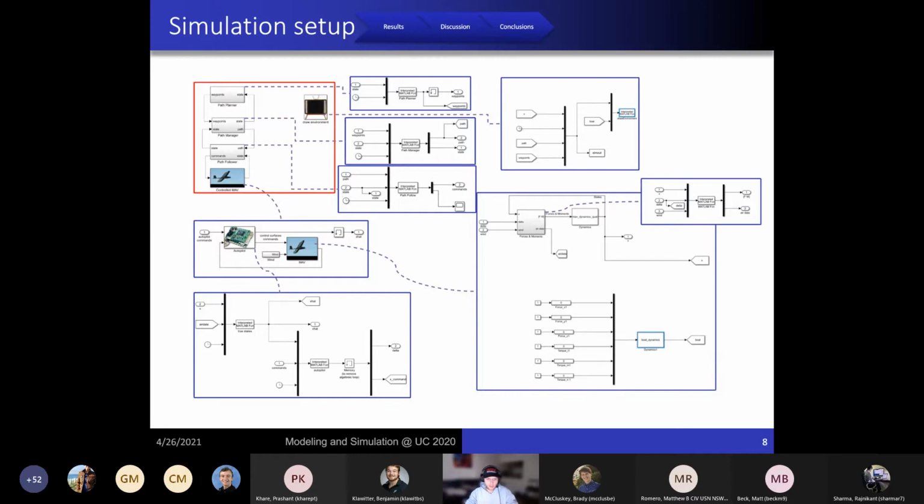As you can see here, we have our simulation set up with some of our Simulink files clipped in, and the lines are connecting the states and how they would transfer through the different Simulink files themselves. Over here we have our waypoint finder, which is GPS, and that then trickles down into most every other aspect of it, going into the autopilot, and then into the dynamics, and really every other aspect. You can see that there's a chain of connections.